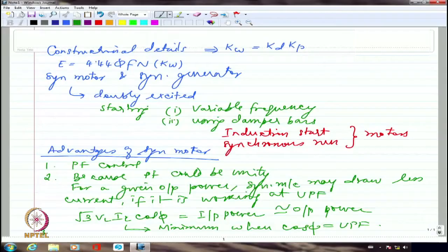If the air gap is more, the leakage will be more. If the leakage is more, to produce the same amount of torque, I might require the same amount of flux linking. If the air gap is more, I might have to produce more overall flux, so that the useful flux is still corresponding to the original quantity when the air gap was smaller.